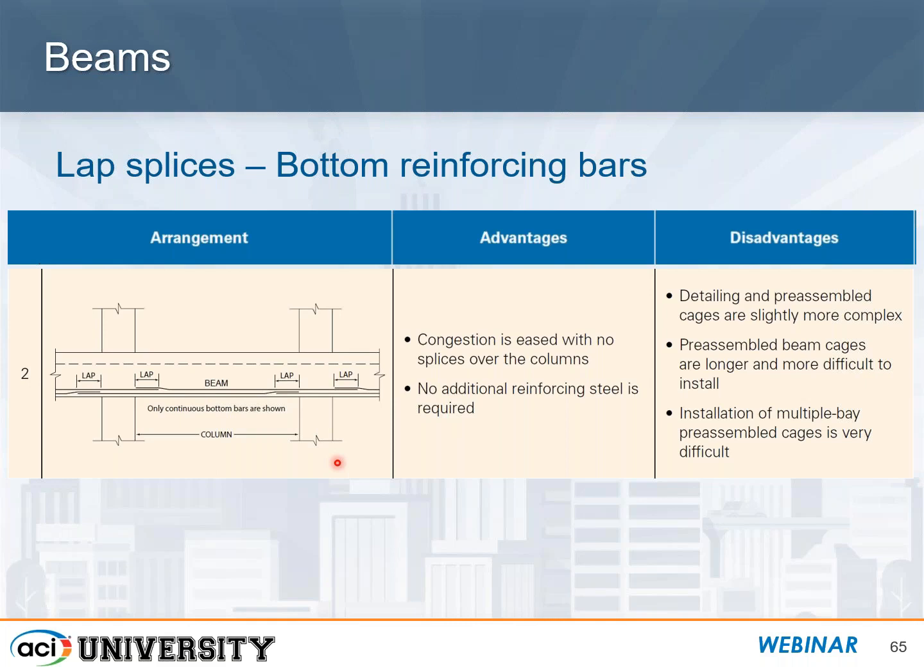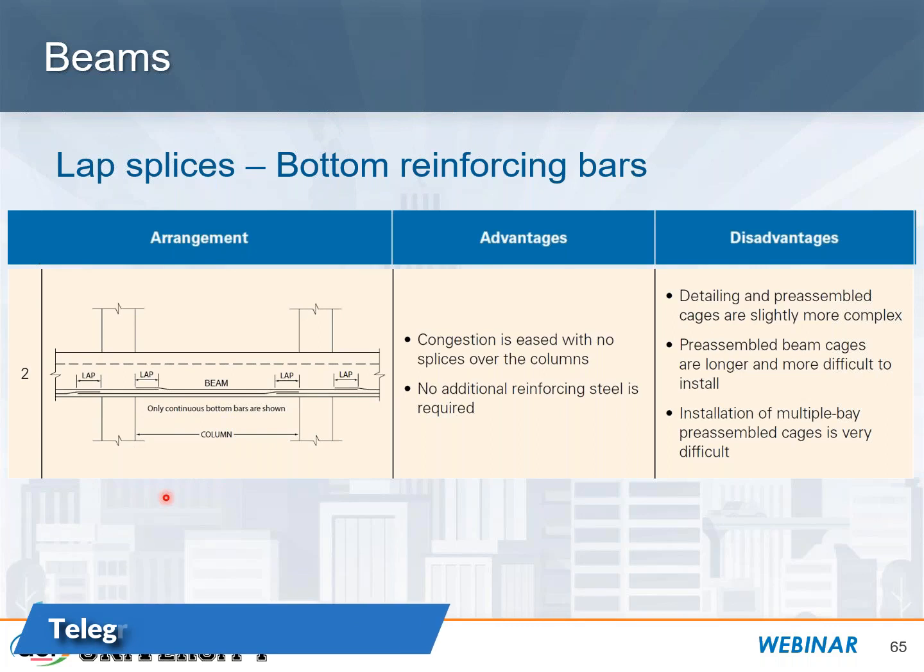If the cages are pre-assembled, having this type of connection to make is really much worse than having the connection we were talking about in the first situation. Knowing that at the onset, you probably aren't going to know until you get the placing drawings back. But just thinking about span lengths and seeing what might be the most beneficial solution is something to think about at the onset.